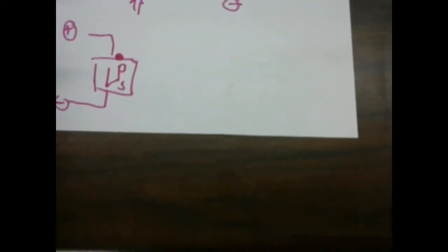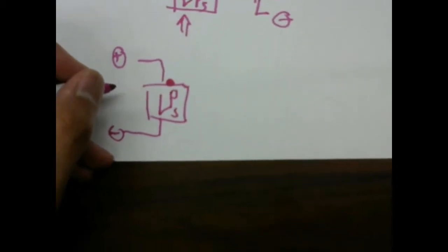The typical convention when they manufacture piezoelectric materials is that when they pole a material, meaning they apply a large field over here and a negative field over here, or ground rather, and then the polarization orients itself like this, they put a dot at the top of the material. You may find that in the piezoelectric materials you have in your lab there's a dot, and that dot represents this positive voltage which is applied. Basically it's the tail of the polarization. The positive voltage is the tail of the polarization.